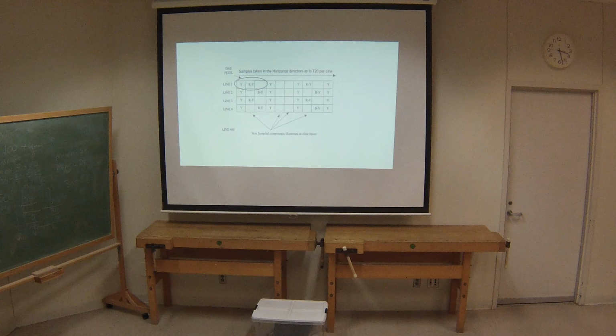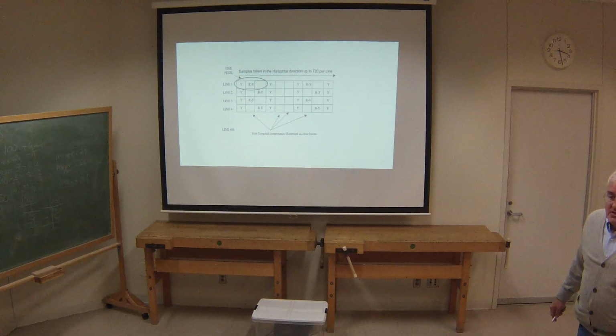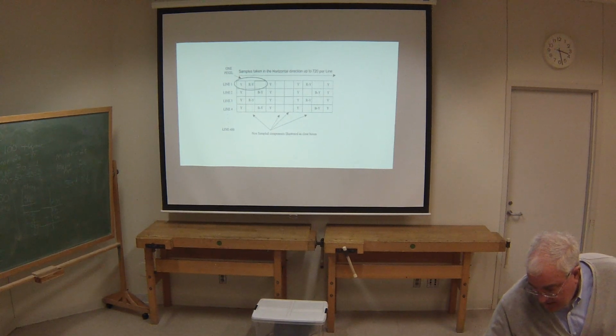So in the end, they basically interpolate all the holes? Yeah, more or less, you could think of it that way. The bottom line is that we threw away 75% of our chroma signal, but notice that we kept all of our luminance signal. All of the monochrome signal is kept.